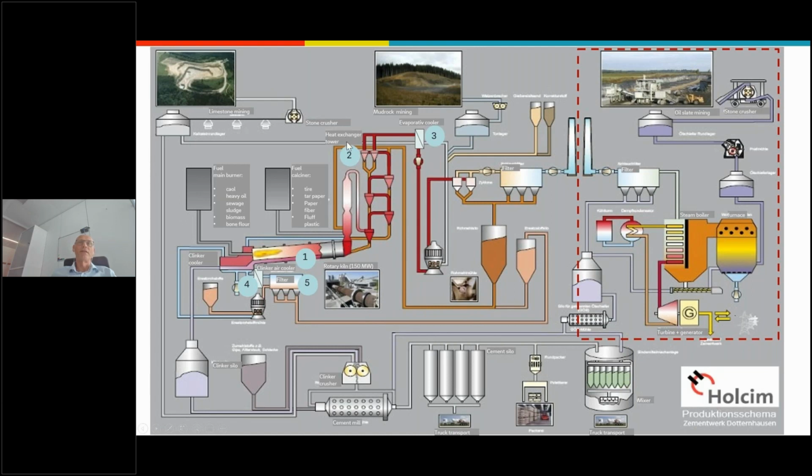The rotary kiln's preheater is a heat exchanger tower. It is called a heat exchanger tower because the exhaust from the kiln is going this way. The material is going from up to down, and the exhaust is going from down to up. So the material is heating up here in every step, and then goes with a temperature from 800 Celsius through the rotary kiln.